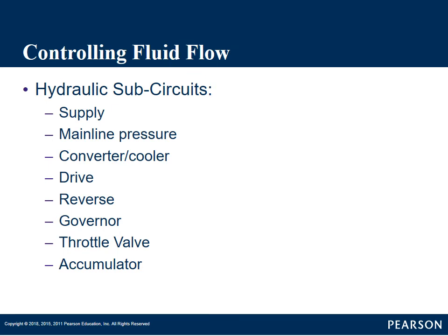Okay, now we're going to talk about the hydraulic subcircuits. And when I'm talking subcircuits, we're talking about the different actual hydraulic circuits within a transmission. First, we have supply, and supply is basically the fluid in the pan that the pump picks up. So the pump picks the fluid up through the filter in the pan or the sump, and it puts it into the pump, and this is our supply circuit.